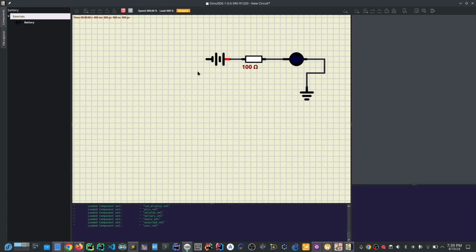Then you click on it, drop it, then join the remaining. I have a wrong circuit design, so I should drop this one to be ground here. Deleting the wires there. For the LED, the best design is to put your resistor toward the ground side of the LED, so you ground the resistor to the LED, to avoid too much current.